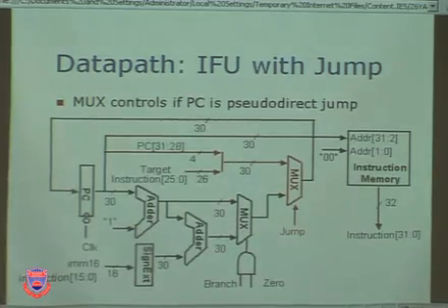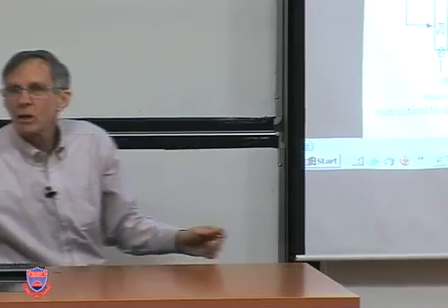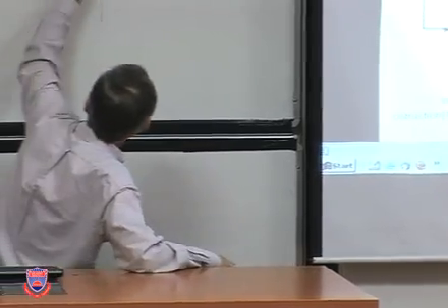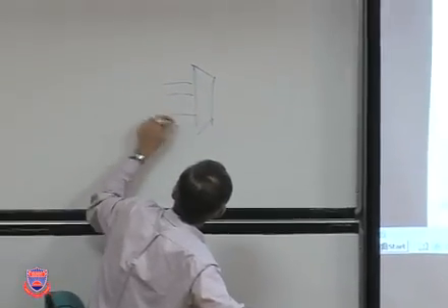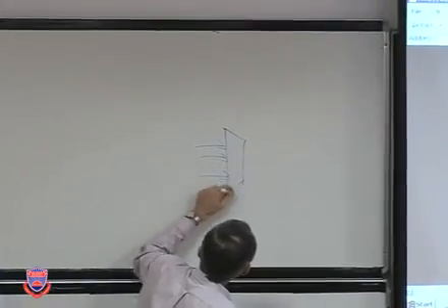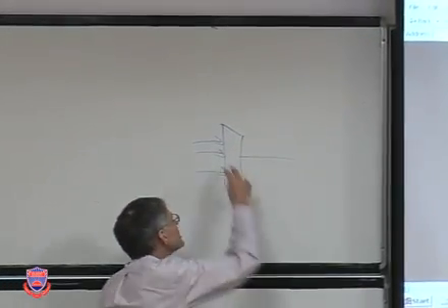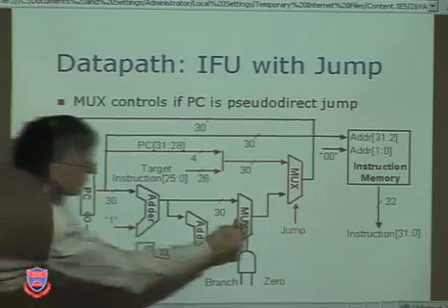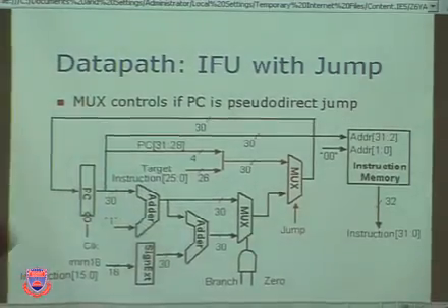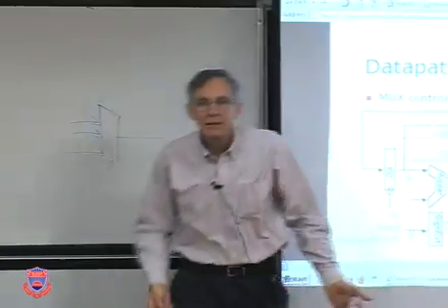That's not so good. Or really a 3-to-1 mux would be better. Everybody know what a 3-to-1 mux is? This looks like this. I got 3 inputs, 2 controls. I choose 1. That's a 2-level circuit. So therefore, that's 4 and that's 2. This is better. It's clearly better.